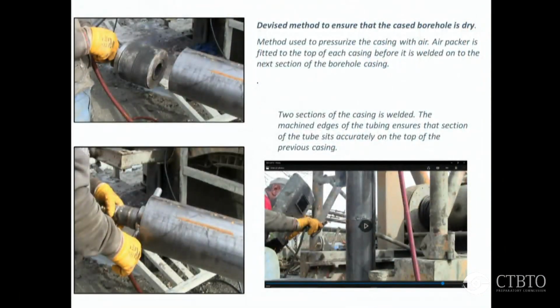But having pressurized it after welding, we just used some soap, just washing soap, to see if it bubbled, and I can assure you it worked very well. So it's a very simple technique one should use everywhere. I was there whilst this was being done.